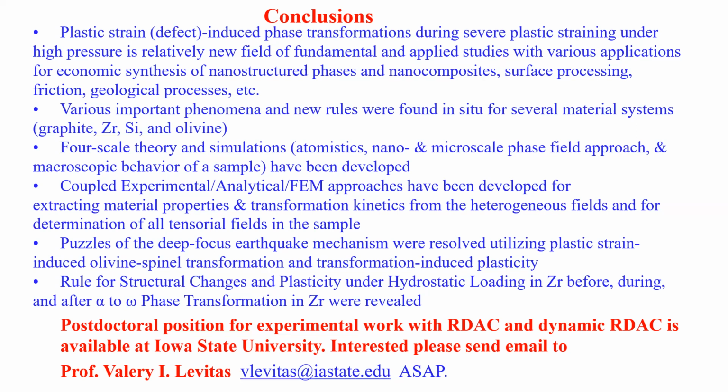But at nanoscale, shear stresses are limited by theoretical shear strength, which is 1 to 2 orders of magnitude higher. So in addition to huge normal stresses, locally we have huge shear stresses. And they satisfy our phase transformation criteria, which is not 1.3 GPa, but about 60 GPa.